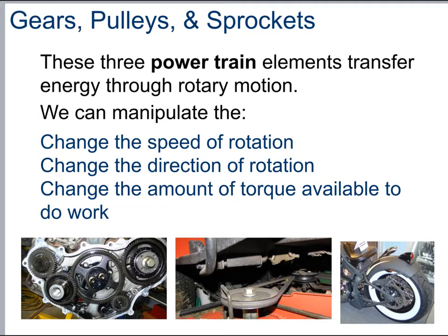Gears are commonly used in many systems, but they can most easily be recognized in everyday life in the cars we drive. Cars must make use of gears in order to transfer energy from the engine to the wheels efficiently and safely. An idling engine operates at about 1,000 RPMs, or revolutions per minute. If the engine was connected directly to the wheels, this would mean the car must be moving approximately 100 kilometers per hour. This means if a car's engine is turned on, it would immediately accelerate to this speed.